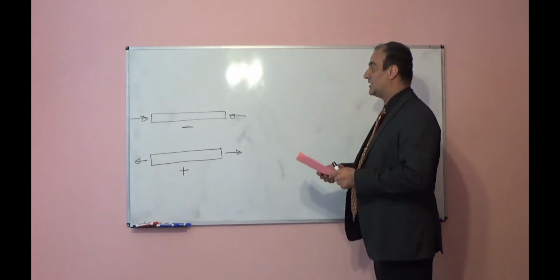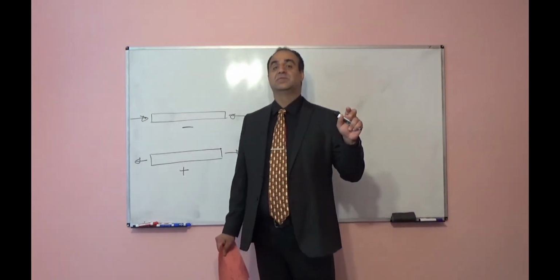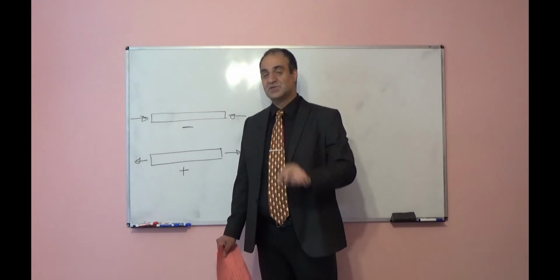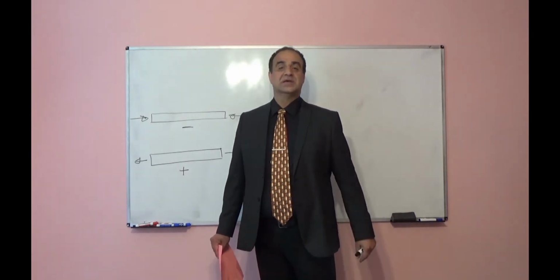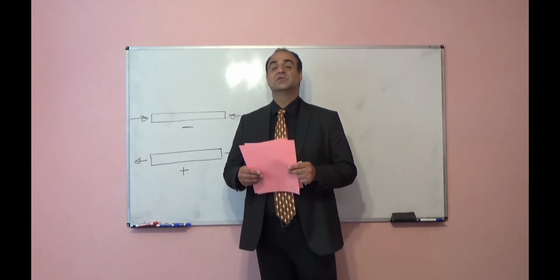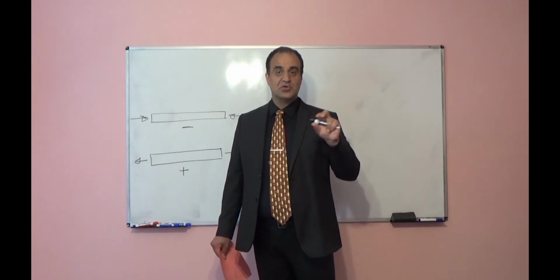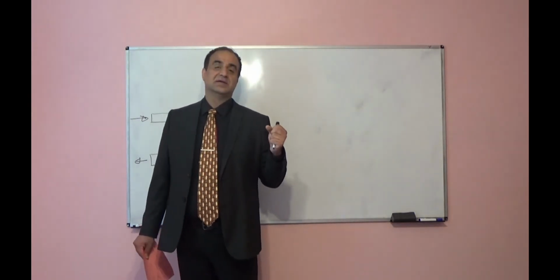The way I now solve the previous example, I cut a joint and start from the joint where we have two unknowns, and I move from that joint to another joint. That way, in order to find internal forces in truss members, we call it the joint method, because I'm cutting joint by joint. There are two ways to find internal forces.